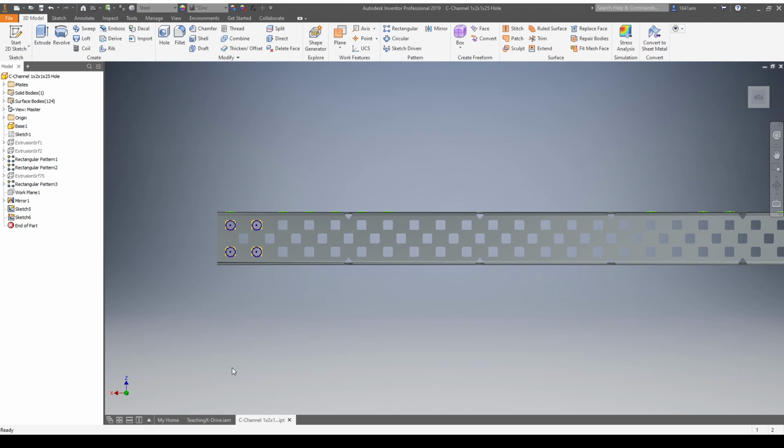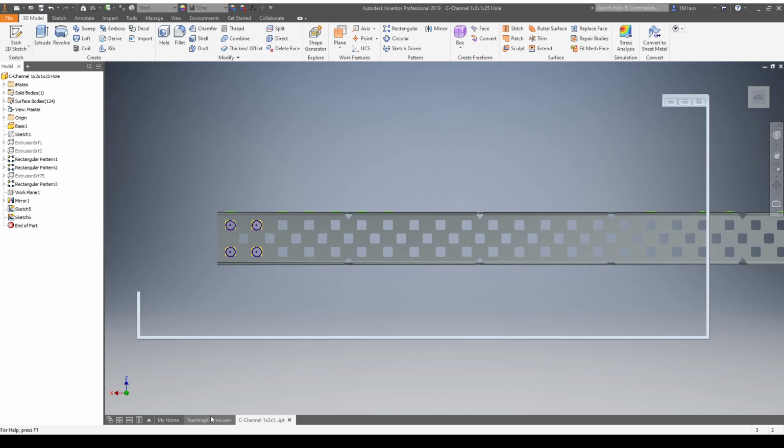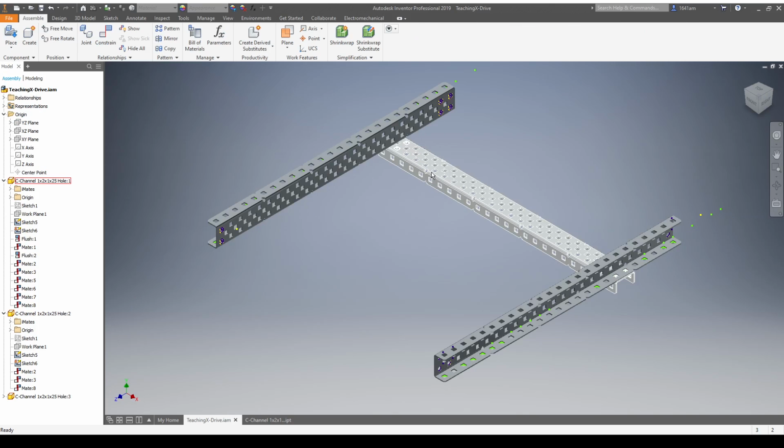Okay, can you share your screen? Okay, so if you did it inside the assembly, the drawing is constrained relative to something in the assembly. It's not actually on the actual part. That's why it's always best to just open the part separately, so that when you make the drawing, it will actually put it onto the part and the drawing will stay relative to the part.